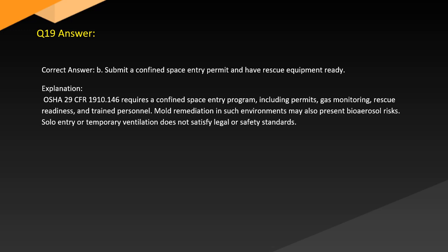Explanation. OSHA 29 CFR 1910.146 requires a confined space entry program including permits, gas monitoring, rescue readiness, and trained personnel. Mold remediation in such environments may also present bioaerosol risks. Solo entry or temporary ventilation does not satisfy legal or standards.